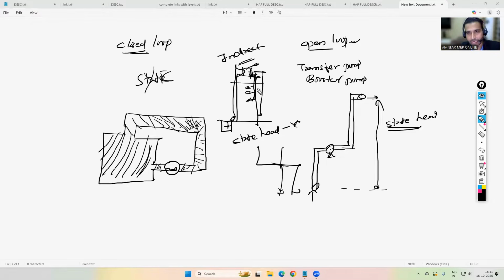So that's why, when we are doing the indirect system of a booster pump, we have to calculate the material losses, the fittings losses, and the residual losses, and add them together. From that value, we have to deduct the static head. Static pressure is negative in the indirect system of a booster pump. Then we will have the direct system as well.